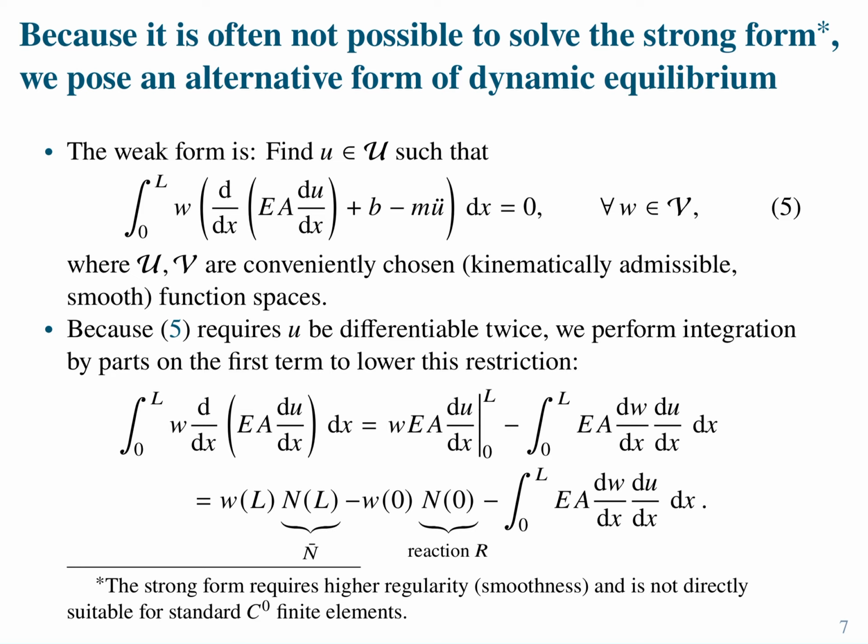But another important thing that happens when we apply the integration by parts is that we have this term popping up, right? And if you recall, EA du dx is actually the force, right? And of course, the force has to be evaluated at the extremes of the bar. So just by doing integration by parts, the Neumann boundary condition pops up in the formulation.